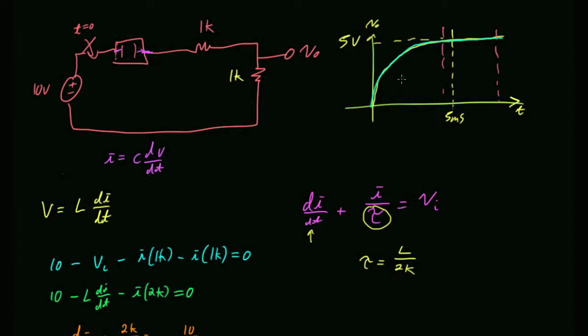Here you're putting in a constant, and the constant is actually getting passed right through. So that low-frequency constant is being passed, which means what you have here is a low-pass filter. And we know a capacitor there gives a high-pass filter, so it can't be that. Yeah, I'll buy that logic.